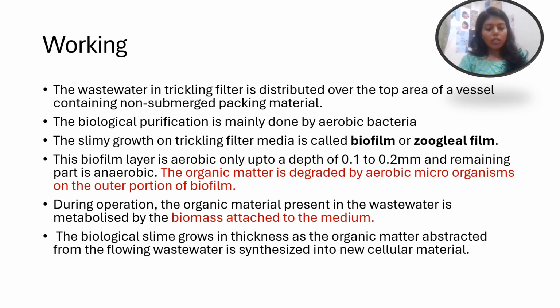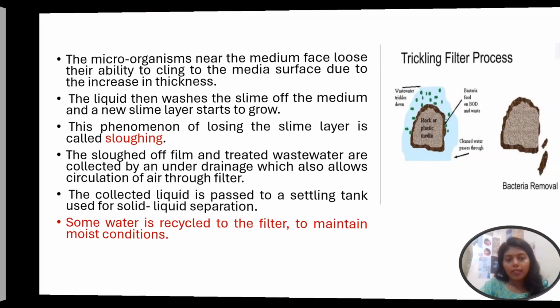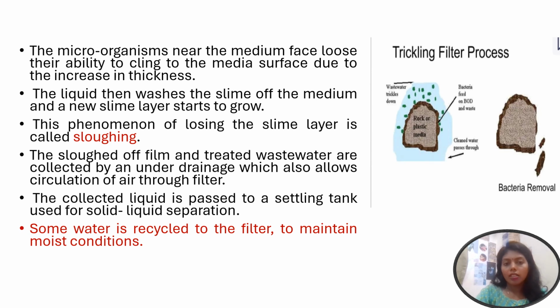Additionally, as treated water passes through the media, they will help to filter out the solids that are present in the water. As the process goes on, the biological slime growth will grow thicker and thicker. So the microorganisms that are near the media will lose their ability to attach to the surface due to the increase in the thickness of the slime.